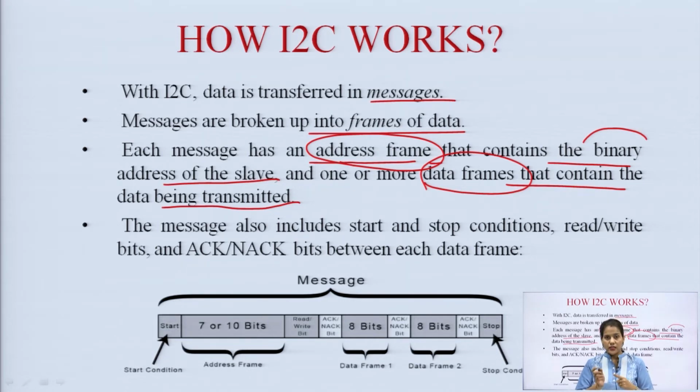When that matching occurs, suppose the first slave has the same address as the one sent by the master device, then it means the first slave is to be selected. So, it sends back the acknowledgement signal to the master. In this way, addressing is useful in selecting a particular slave.